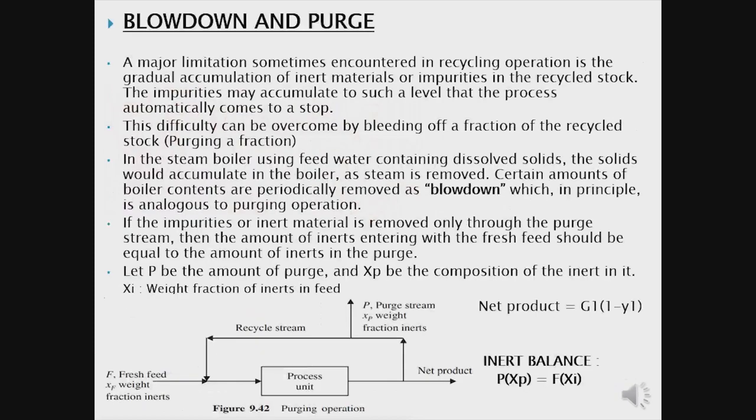Now the final topic of this module is the blowdown and the purge. The major limitation sometimes encountered in recycling operations is the gradual accumulation of inert materials or impurities in the recycled stock. The impurities may accumulate to such a level that the process automatically comes to a stop. It is one of the greatest disadvantages of recycling operations, that is, the accumulation of inert materials or impurities in the recycled stock. Since it is partly returned to the unit again, certain materials, like inert materials, may get accumulated in the recycled stock. So in order to overcome this difficulty, we use the blowdown approach.